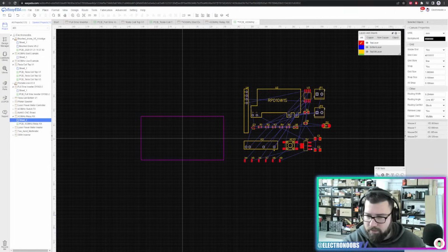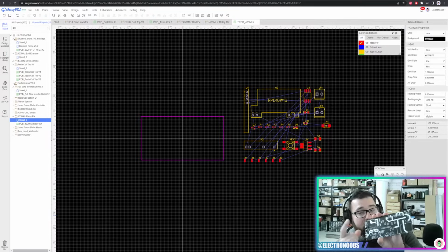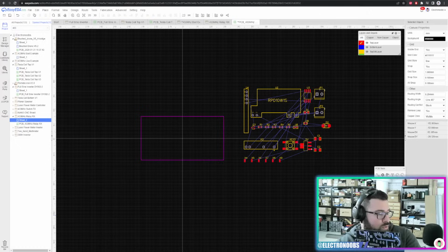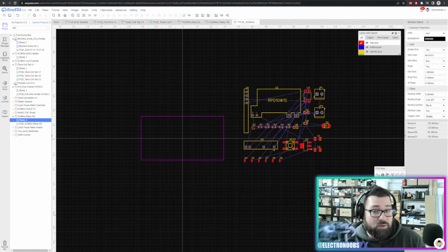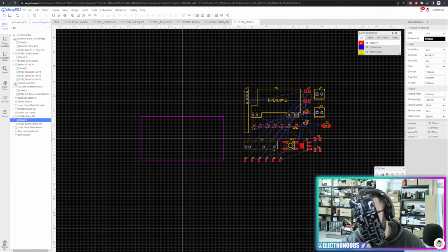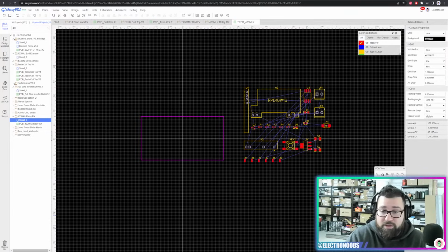Well, actually this PCB that we'll go over in a few moments, this is an inverter. So what you want to do first is get the voltage of your battery, create high voltage. In this case you want 120 volts AC, so maybe you have to create 220 volts. You store it into some capacitors, and then using IGBTs you create the AC signal, which could be a square signal, or in this case is an SPWM that will create a sinusoidal signal. So maybe this will help you. So this weekend I'll post this project and maybe this will help you, because it is a high voltage inverter. From battery it goes to, in this case, 220 volts AC.